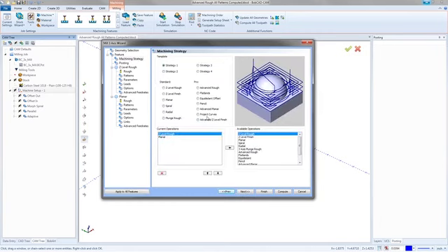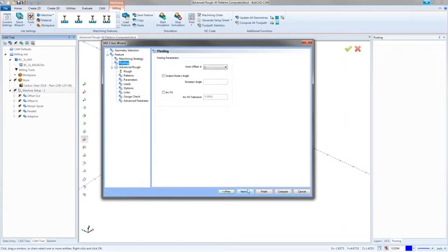Next, we then have the machining strategy tab. Now on this strategy tab, I'm just going to look at the advanced rough and we're going to go through it. So next. So the posting tab, the only real important thing for most people on this page is the arc fit button. If you do not click the arc fit button, all of your G code is going to come out as line moves instead of arc moves. There's going to be no arc moves in the program.